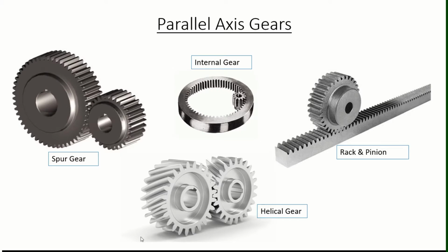And the helical gears are the ones which are used with parallel shafts, similar to the spur gears, and they also have the cylindrical gears with winding tooth lines. They have a better teeth meshing than the spur gears, and they have a superior quietness, and they can transmit higher loads as compared to the spur gears, and that makes them suitable for very high speed applications.